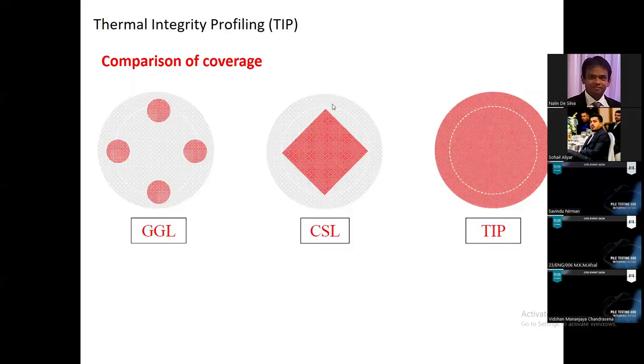But cross-hole sonic logging is popular in Sri Lanka. You can detect any defect within this region, right? Outside the cage, you cannot detect any issues. But the thermal integrity profile, TIP test, has 100% testing coverage. You can detect any defect within the cross-sectional area of the pile.